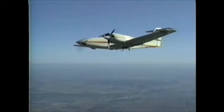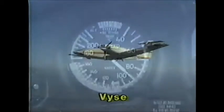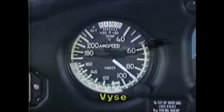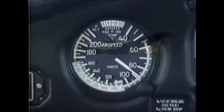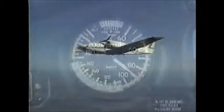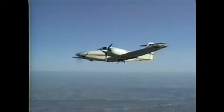The best single-engine rate of climb speed, VYSE, sometimes called blue line airspeed, has several applications to multi-engine flight. It gives you the best rate of climb, or the slowest rate of descent if you can't maintain altitude. Another application of VYSE is in connection with the single-engine service ceiling.